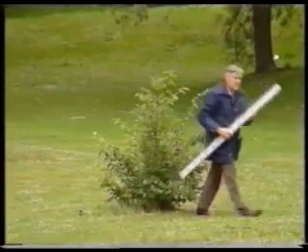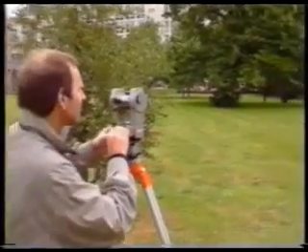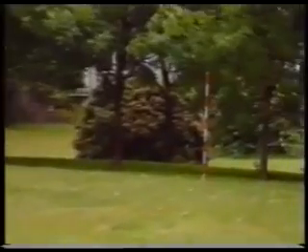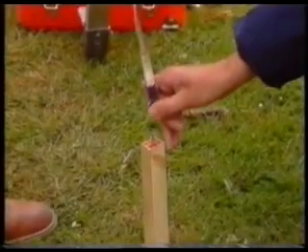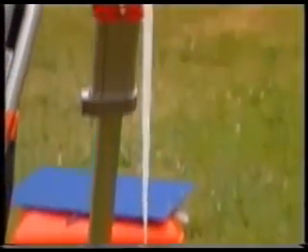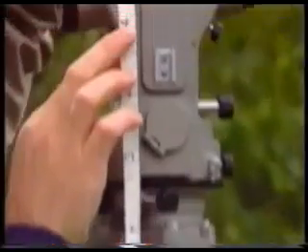When all the observations have been made, the orientation of the horizontal circle should be checked to ensure that it has not changed by resighting control point B. Finally, before moving the theodolite, the height of the trunnion axis above the known reduced level at control point A is taken.